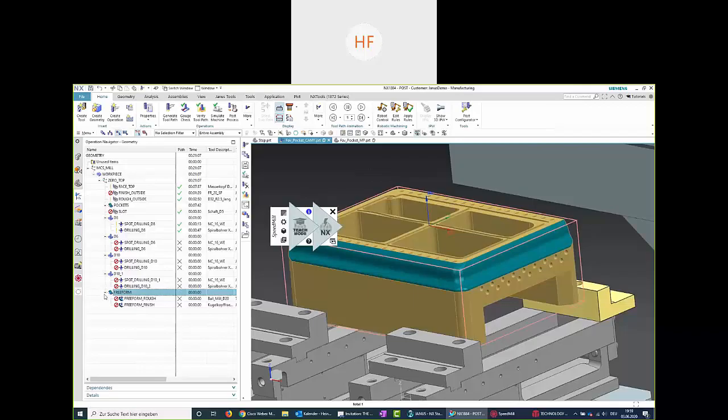There's a third expression that's called clamping height. For now, it's set to be 35 millimeters. When I reduce it down to 0, I see that the part now is on its right position. Let me show you the blank material once more. There we go. We see the clamping height is down to 0 and those vices are on their correct place.